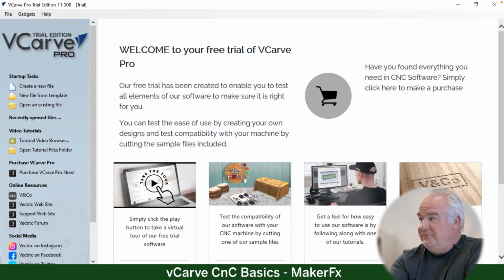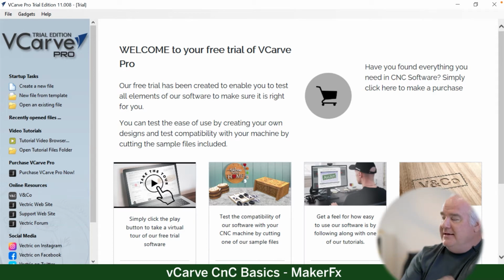That file is called a G-code file. So it has an extension of .cnc, but inside of it are G-code commands. Another tool chain, which if you want to use this, we can get some other members to help you learn it, is Fusion 360. Design in Fusion 360, toolpath in Fusion 360. Fusion 360 creates the G-code file, and then you load it on the machine and run it. So if you happen to know that application and want to use it, that's an option for you. And as Rachel asked, there's a variety of other options on the design side to create vector drawings. So today, what I'm going to cover is that basic tool chain of using VCarve Pro.